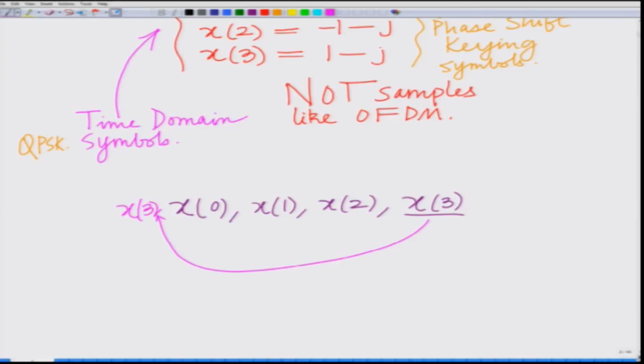We have seen this many times before. In the sense that we are adding this cyclic prefix prior to transmission, it is similar to OFDM. Remember, in OFDM also we add the cyclic prefix. However, the important difference is, while in OFDM we take the IFFT of the symbols and transmit the samples, in FDE we take the symbols and directly transmit them after adding the cyclic prefix.